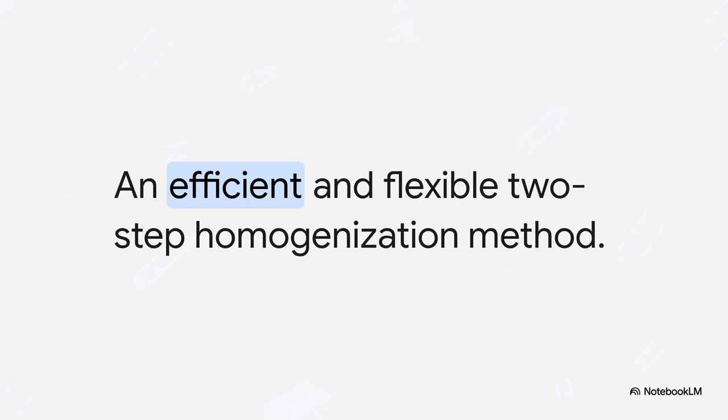Step 1, get the unit cell properties. Step 2, statistically average them based on orientation. It entirely bypasses the need to geometrically pack thousands of fibers into a single mesh. You can use literally any fiber aspect ratio, any volume fraction, and any orientation distribution without breaking a sweat. It's a real game changer.